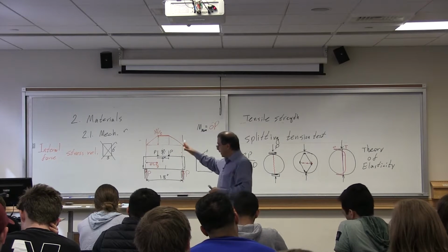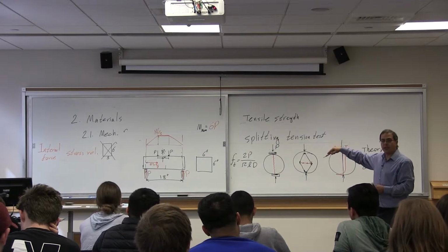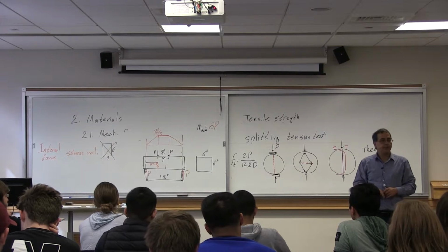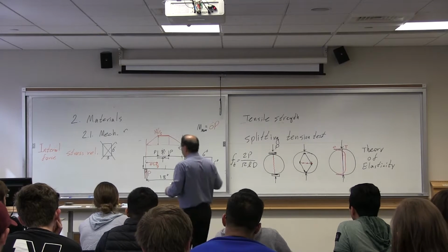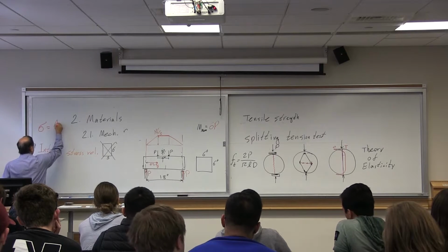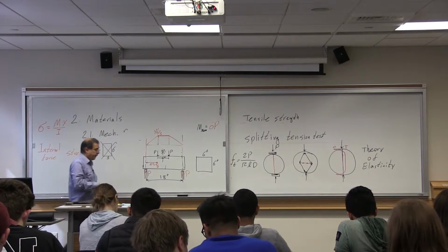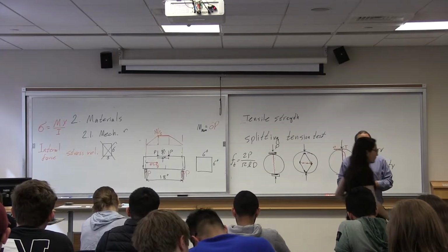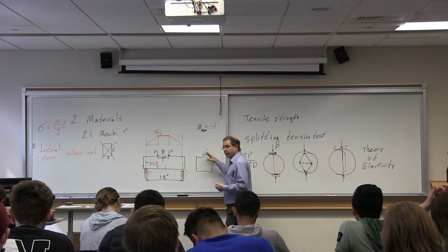You need a different internal force-stress relationship. So what is the stress-internal force relationship for a rectangular section under moment? Stress is equal to My over I. What is y? The distance from the axis to whatever point where you are calculating the stress.